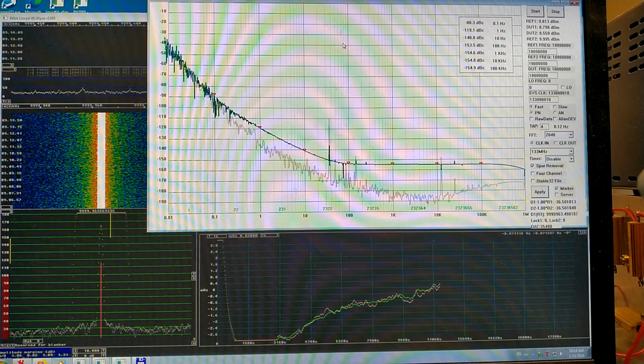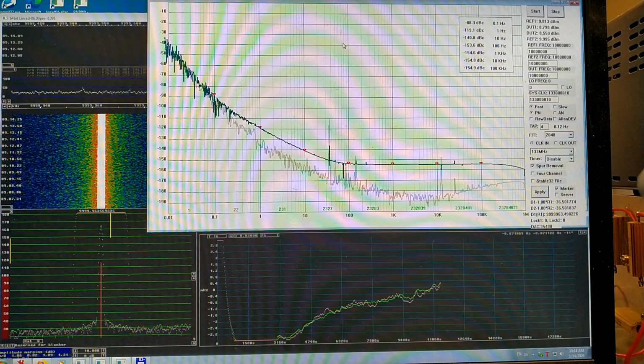That is placing the zero frequency at about 30 Hertz, because the Wenzel is about 10 Hertz above 10 megahertz. With a 30 Hertz offset from zero, I can accurately measure phase noise up to 29 Hertz. And now it's only up to 9 Hertz with the Wenzel oscillator. Because I need the Wenzel oscillator for tuning the oscillators that I am working with.